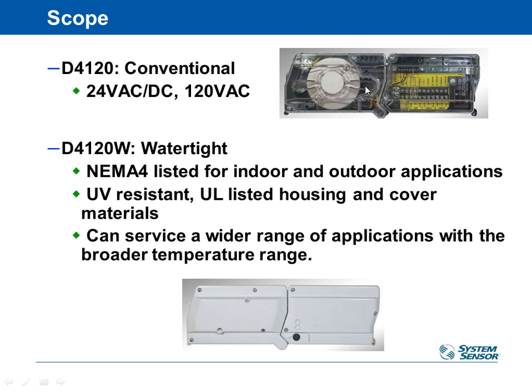It's not that much more. I want to say off the top of my head it's like $20 more than a regular smoke detector. So if you have an outdoor application and you want to do it, the detector will not be cost prohibitive. Now you still have to do all your conduit and watertight connections and all that. So obviously you want to install it indoors when you can, but if you have to put it outside, it's doable.